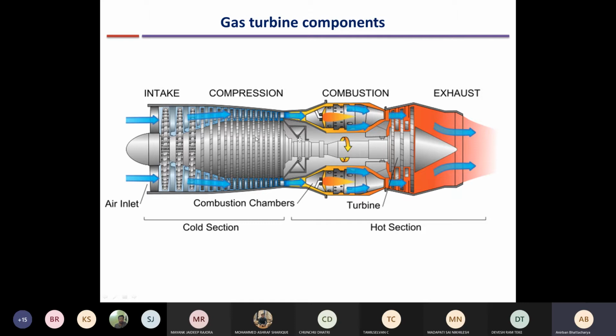Yes. So specific volume is very high means V delta P, which is the work input, the integral of V dP, becomes very high. Delta P we can keep the same, but because the specific volume V is very high, the work input becomes higher. So your answers are correct, but not exactly to the point. For pumps, the specific volume is very low. So even if the delta P is the same, the work input will be low. But in pumps, we generally have a much higher delta P for a steam turbine plant. Still, the work input is low. But in this case, the work input is quite high.